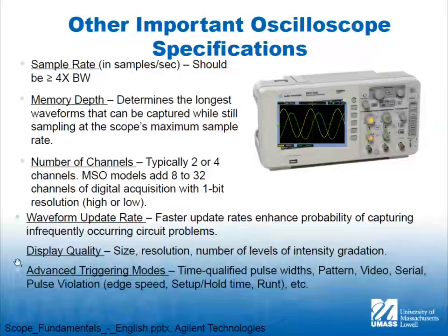So how often can we update the waveform, what the display looks like? You can get a really good oscilloscope with no display these days. It just connects to USB. And then triggering modes. Now, I've been implying that the trigger is rising edge or falling edge, but there's lots of other things you can do with triggering. And for the oscilloscope, I don't care. I'm going to give you some information about that for logic analysis. But just know that the scopes and the logic analyzers come with some advanced triggering methods.